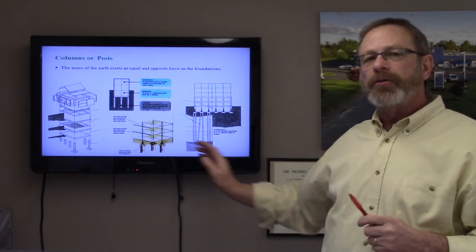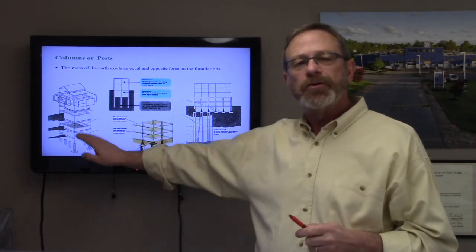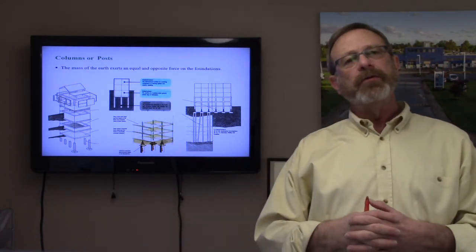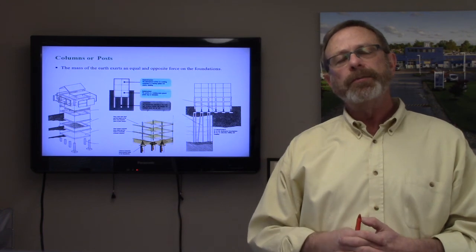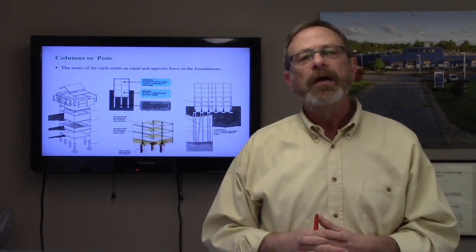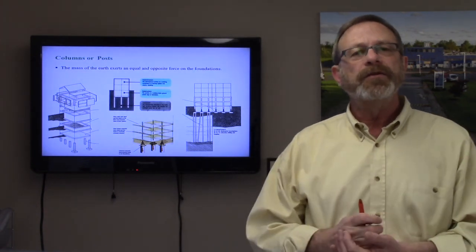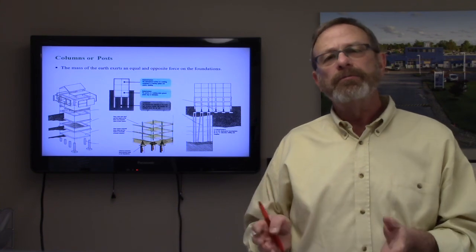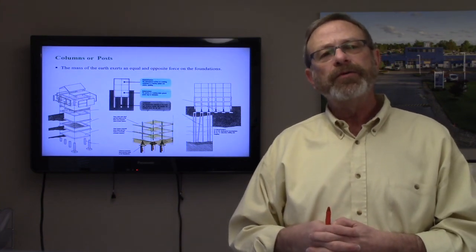So in other locations, maybe a house, we have short footings that go down only as far as necessary to reach virgin or undisturbed earth, and that's earth that's been compacted over millions of years, undisturbed, and has achieved its maximum compression, and any load that we add on to it is most likely going to be resisted.